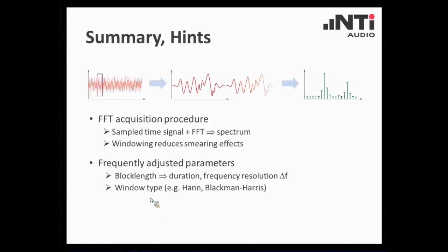Second, the window type. These are the two windows that are supported by the FX100, or you may also switch it off. And the x-axis scaling, linear or logarithmic, that may give you some valuable information about the behavior of your device under test. Last but not least, the averaging feature that would allow you to smoothen or to stabilize the displayed result in order to make the readout easier.